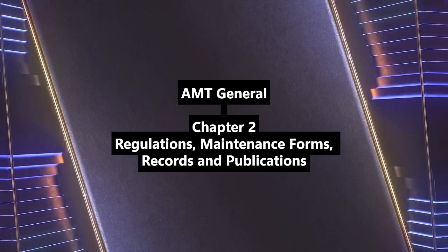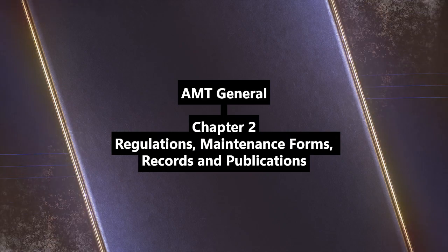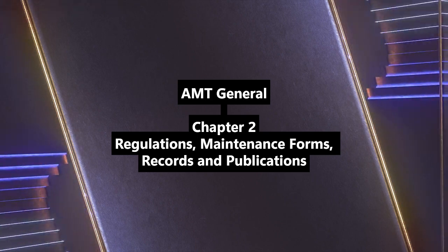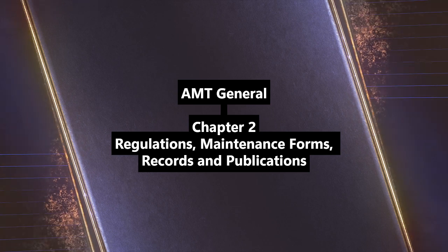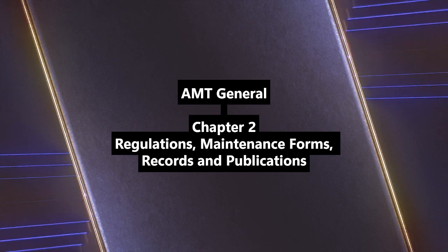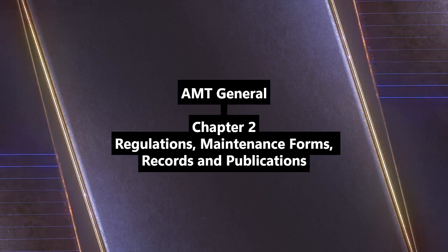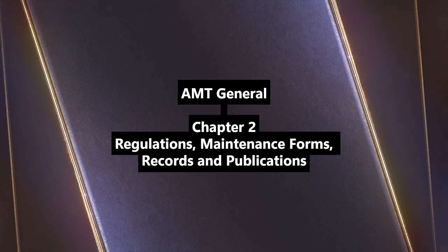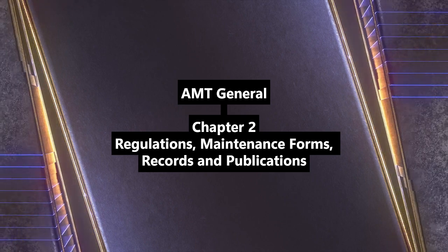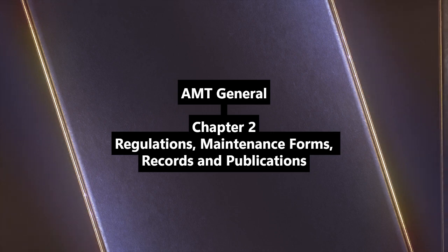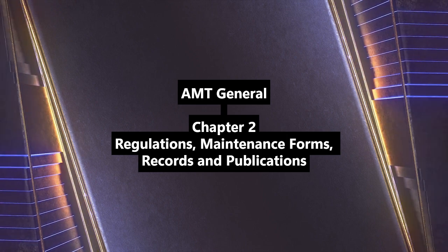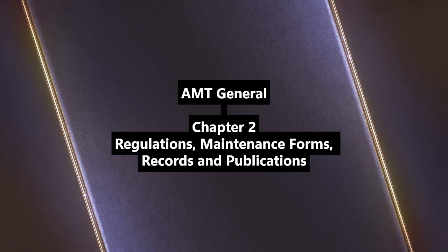This sounds important. Very. It defines life-limited part and life status. It dictates how you handle parts that have a mandatory replacement time or cycle limit. What are the requirements? The person removing the part is responsible for controlling it and tracking its life limit using one of 7 methods: record keeping, tagging, non-permanent marking, permanent marking, segregation, mutilation, or another FAA-approved method. And that life status info has to follow the part. Absolutely. It must be transferred with the part. This rule is really about managing parts after they're removed.